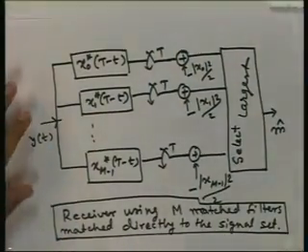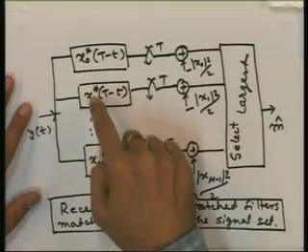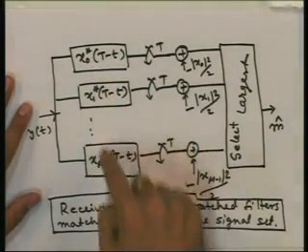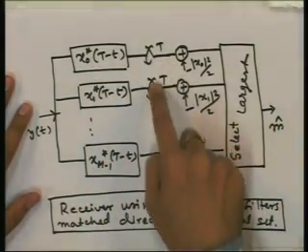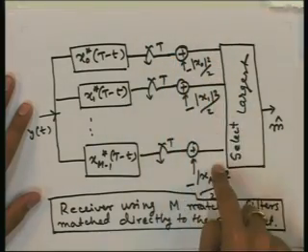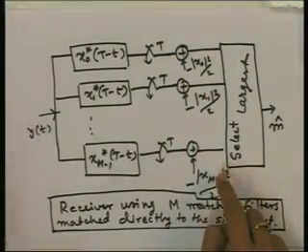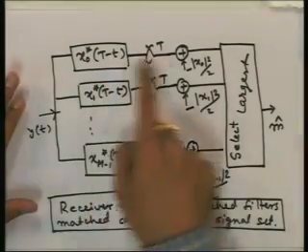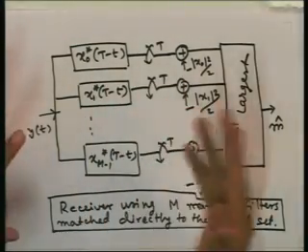So, here we use these matched filters matched to the different signals, and then sampling we will get the outputs. Now, we can compare directly. We have also derived and shown that this will do the same operation as a correlation receiver or matched filter receiver using matched filters matched to basis signals.